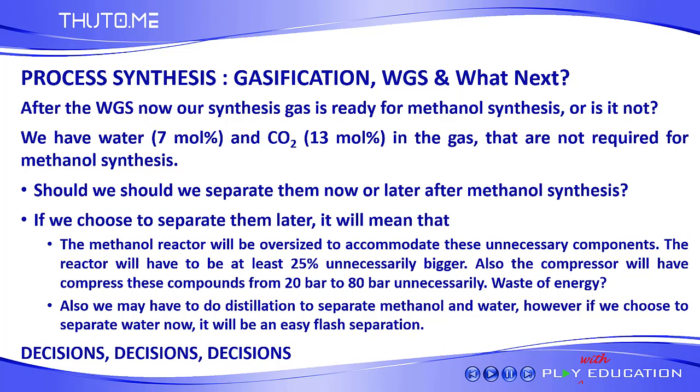Separation of these gases and water will just be cooling down to a lower temperature where water will condense, and then I'll separate the water. And then what do I do with the CO2? Do I let it go through the methanol synthesis reactor, or do I separate it right now? All these decisions, you need to consider while you are doing your process synthesis, and you need to justify them every step of the way.